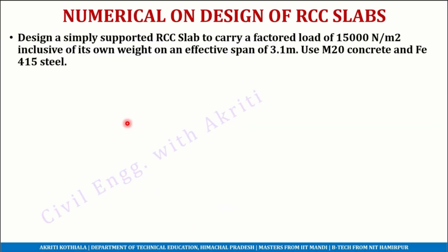So moving on to a numerical problem. This is the problem: design a simply supported RCC slab to carry a factored load of 15,000 Newton per meter square inclusive of its own weight on an effective span of 3.1 meters. Use M20 concrete and Fe415 steel.